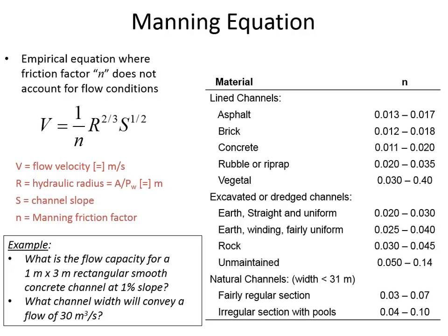For me, I just type it in my calculator and find out that the width B is 4.264 meters. And so that is the width that you'd need in order to get 30 cubic meters per second. And if you substitute that B value in each of the locations where we need to know it, then it works out to 30 cubic meters per second.